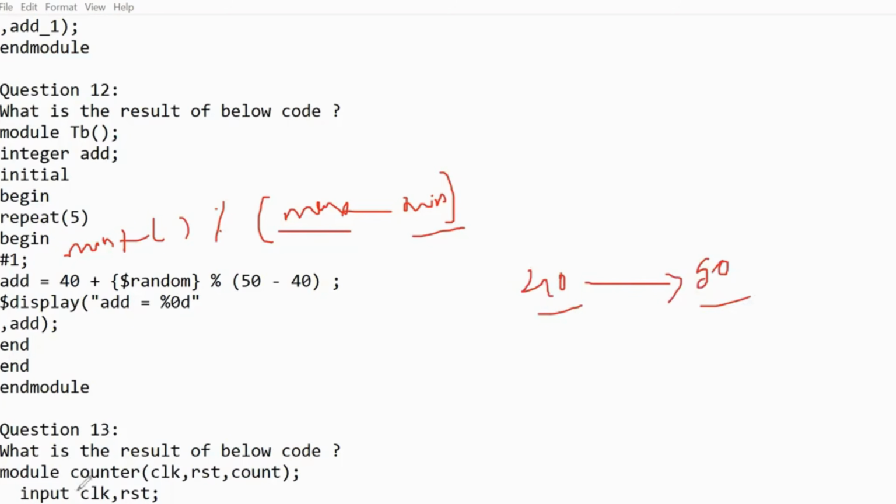Yes, ma'am. You can try all these things using EDA Playground. Then you will understand how these values are generated exactly. You can put signed, unsigned, and generate minimum to maximum. In Verilog, we can use only the $random. But in SystemVerilog, which is an advanced level, we can randomize there and we can control the randomization there.